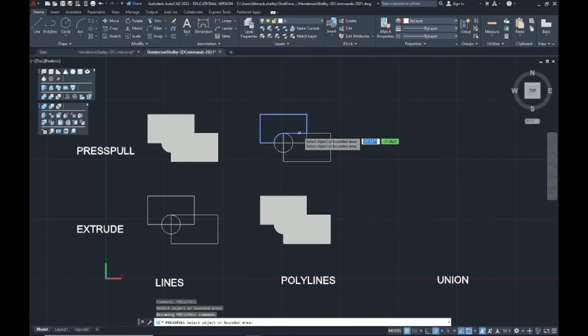And again, you'll notice as I move my mouse through the shape made out of polylines, it doesn't grab the polyline shape. Because remember, if I hover my mouse there, you can see the rectangle is a full polyline, but when I move my mouse inside of the regions here, just like with the shape drawn out of lines, it only picks up the region that is closed there. So it doesn't really care that I've made a 2-point rectangle. It's only going to grab the shape on the inside of this overlapping geometry.